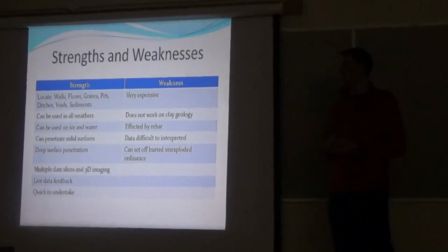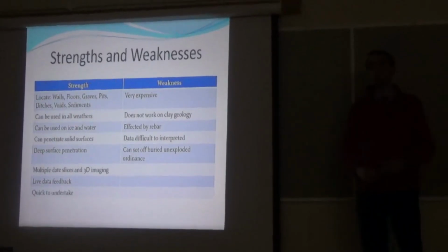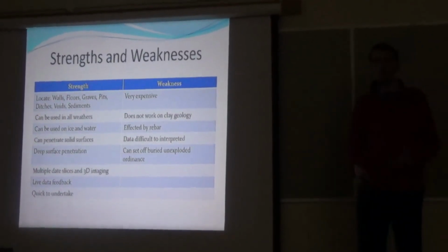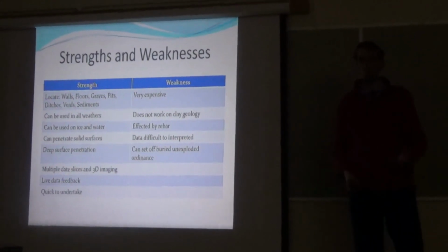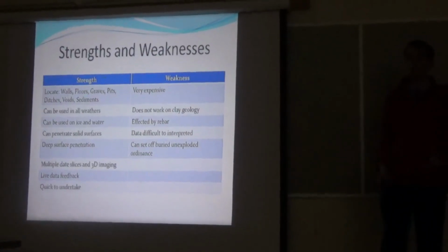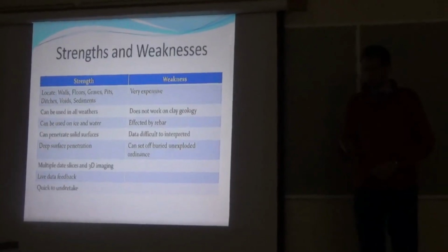The other slight health and safety problem you have is that it can set off buried unexploded ordnance, so bombs. So it's not very good to use in London or urban areas or Southampton docks, anywhere that was bombed during the war, because you don't want to blow yourself up, particularly.